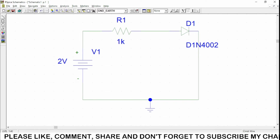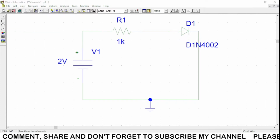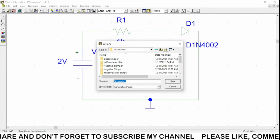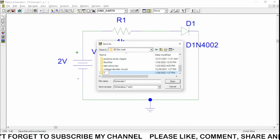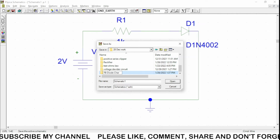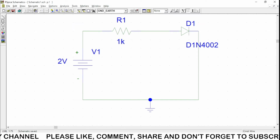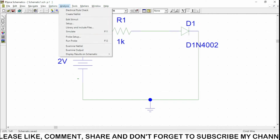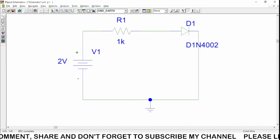What we need to do first of all is save it. So File, we can save it. Saving is also very important. I am going to make a folder known as forward bias diode characteristics. So by naming it, it will be easily found, or it will be easily available in your computer. Then analysis, electrical rule check for any errors if they are available.